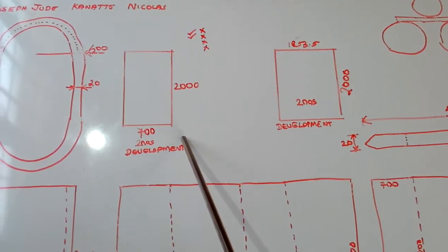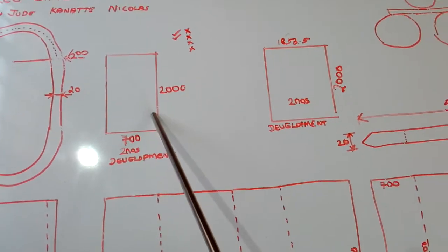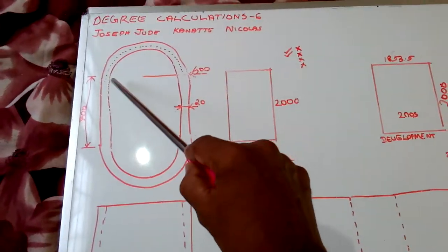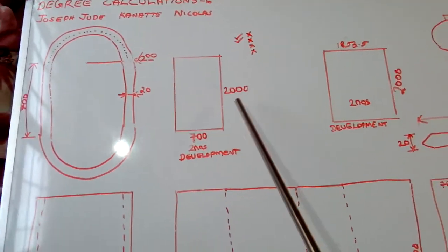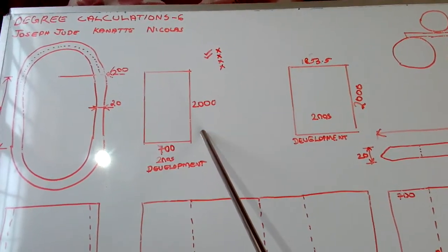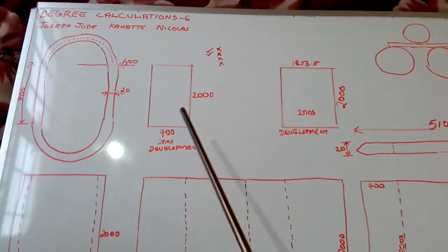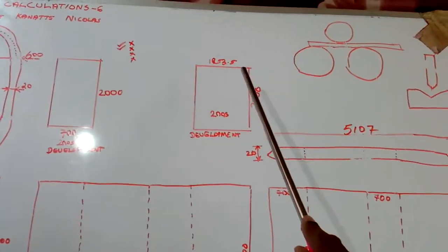It is also a development, but this kind of two numbers have to be made, one for this place and another one for this place. And we have to give bevel, we have to do all setting works, all welding works here also. So we have to take two plates like this, two plates like this also.